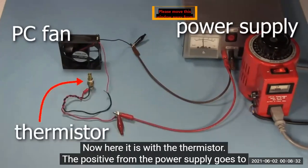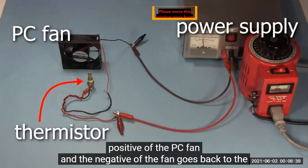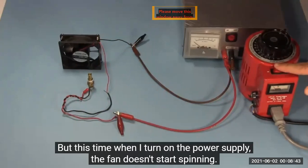Now here it is with the thermistor. The positive from the power supply goes to one end of the thermistor. The other end of the thermistor goes to the positive of the PC fan, and the negative of the PC fan goes back to the power supply. But this time when I turn on the power supply, the fan doesn't start spinning.